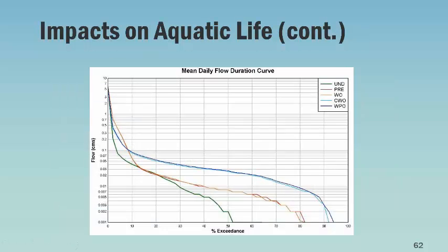And here we talk about the aquatic life. So again, with the implementation of the BMPs, you are able to extend the low flows all the way to almost 90 to 95% of the year because of all the various measures that you can put on the landscape to reduce and slow down the peak velocities and have more water in the river more time than even at the pre-development. Right now you can see only 50% of the time that creek is flowing when there is a rain actually. The remaining 50% is not even flowing actually.